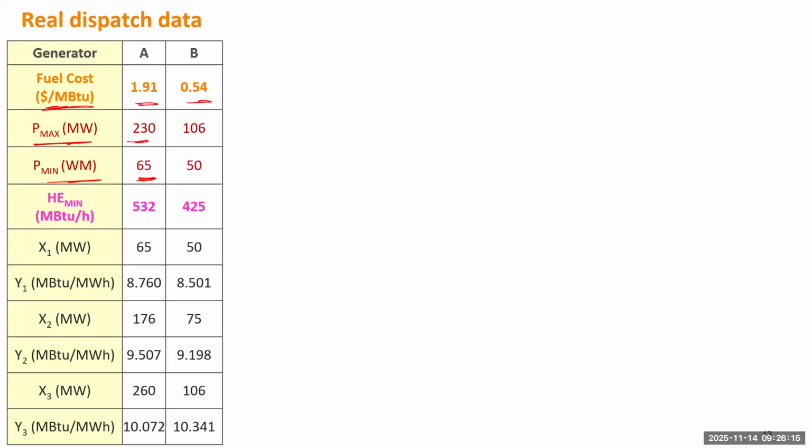Once you decide to start any power plant, you need to quickly run or follow a certain ramping up curve until it can reach the minimal generation. That cannot be interrupted. You have to continually increase the output until that minimal value. Then you have more flexibility to change the generation between the minimal and maximal.